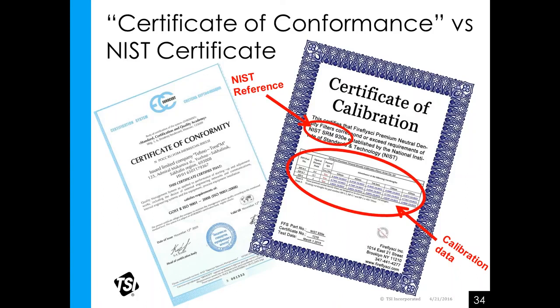Those adjustments were required to bring it into the published operating specs, published by the manufacturer. So it is important to look and see, do I have as found and as left data for my instrument if there was an adjustment made. If there was no adjustment made, you'll have as found and as left data, and you'll see immediately that they're within spec. So it's important to know the difference between the two certificates. And if you're getting charged for this, ask for your money back.